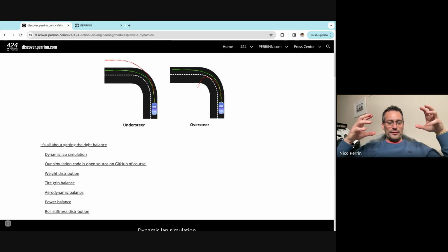You hear sometimes drivers say the car feels disconnected. In Formula One, some drivers would say today the car felt disconnected. When they say that, what they mean most of the time is that they might have a very variable balance, understeer, oversteer, through the corner. In F1, typically you can get quite an oversteer balance on late entry. So when you're trail braking, so you're still on the brakes and trying to make the entry of the corner, the car can be quite loose at the back and will oversteer.